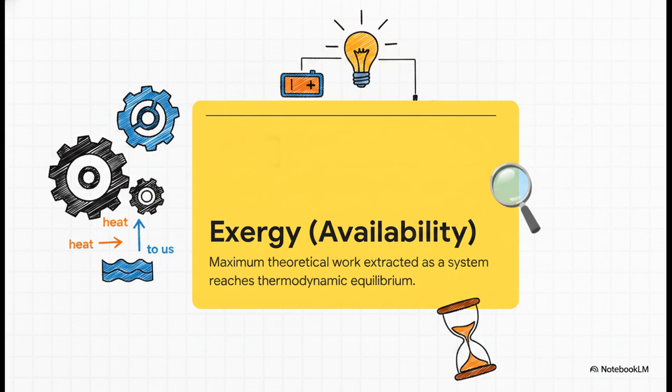Simply put, it's the maximum theoretical work we can extract from a system as it finally reaches thermodynamic equilibrium with its environment. It's not just about how much energy is sitting there. It's about measuring the true quality of it. Basically, how much can we actually harness before it becomes entirely useless to us?